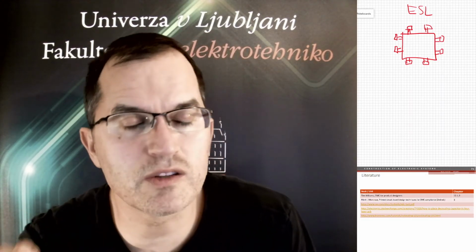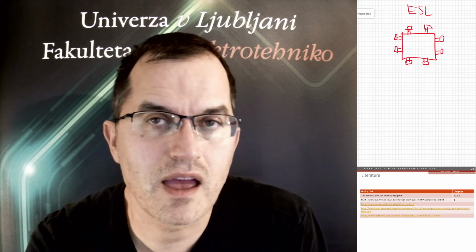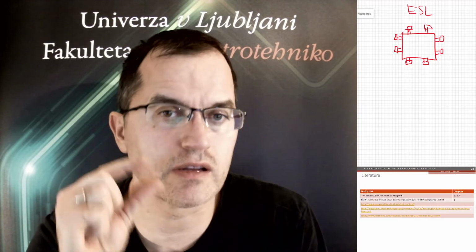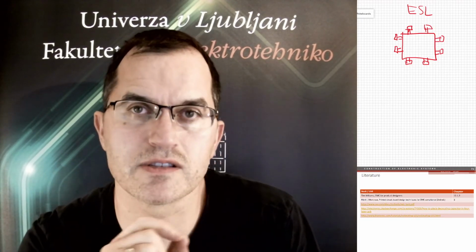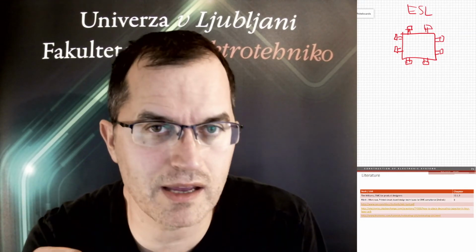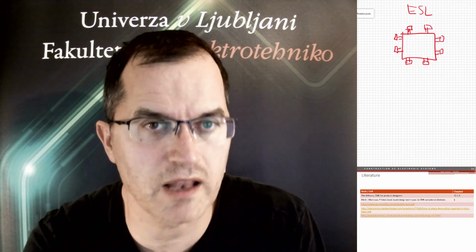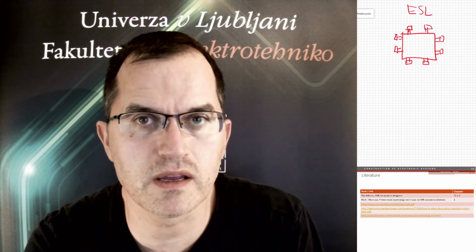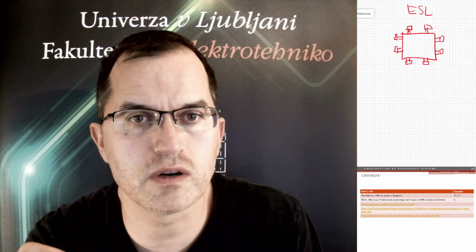But the only one that really knows what is inside is the manufacturer. And therefore, they prepare the ground and power pins for you to place the capacitors next to them. They also state in the datasheets how many capacitors, what the value of these capacitors should be, and the placement. So be aware of that and follow their instructions, because this is the only way to finish your design properly.